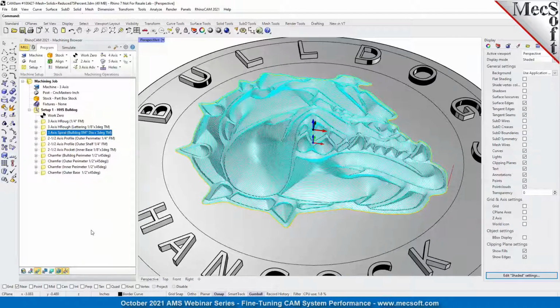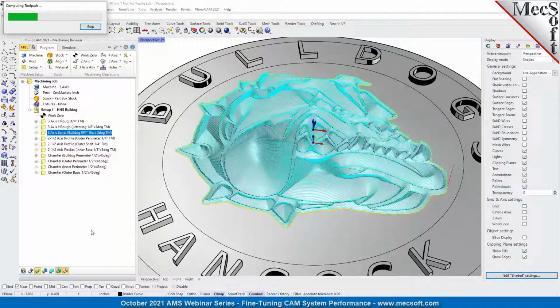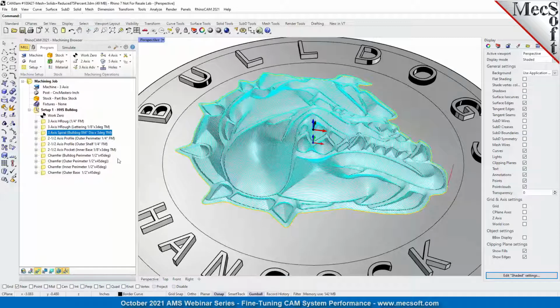This is 50,000 mesh triangles. And when I tested it prior, it was about half the amount of time, about 15, it's already done, 10 seconds. So if it's allowable that you can slightly reduce the quality of the mesh, but still get represented what you need to get represented by lowering the density of the mesh, that's definitely what you want to do because it will save you on resources every time you use it. Okay, so let's go back.